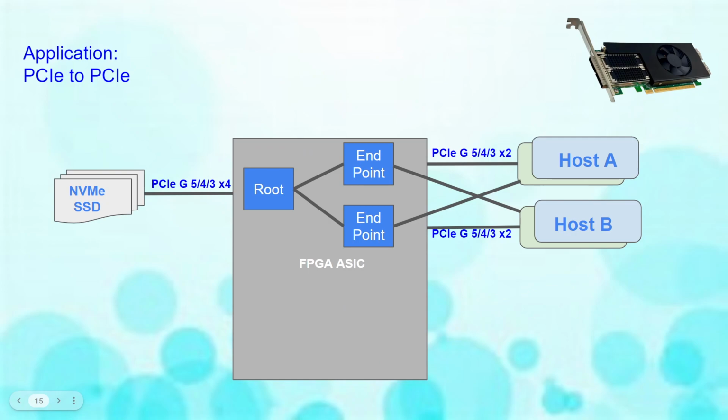Here is a sample application supporting two PCIe Gen 5, 4, or 3 hosts from the endpoint with one NVMe SSD through PCIe Gen 5, 4, or 3 x4 from the root.